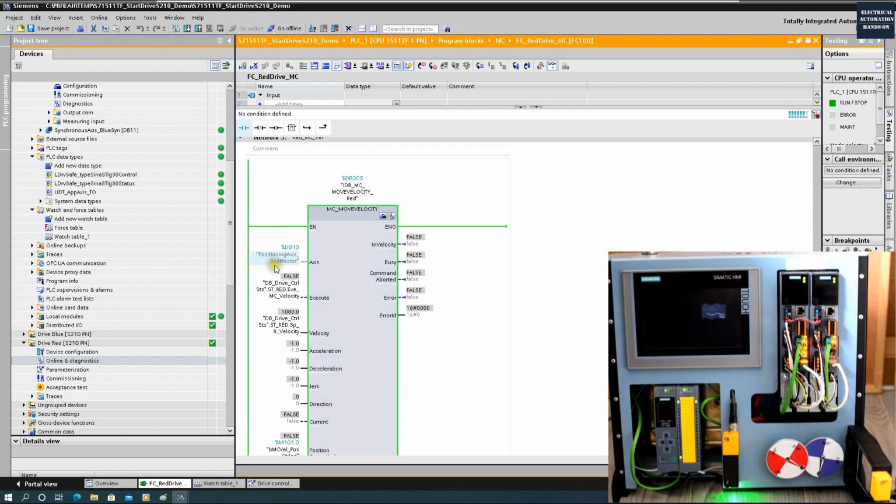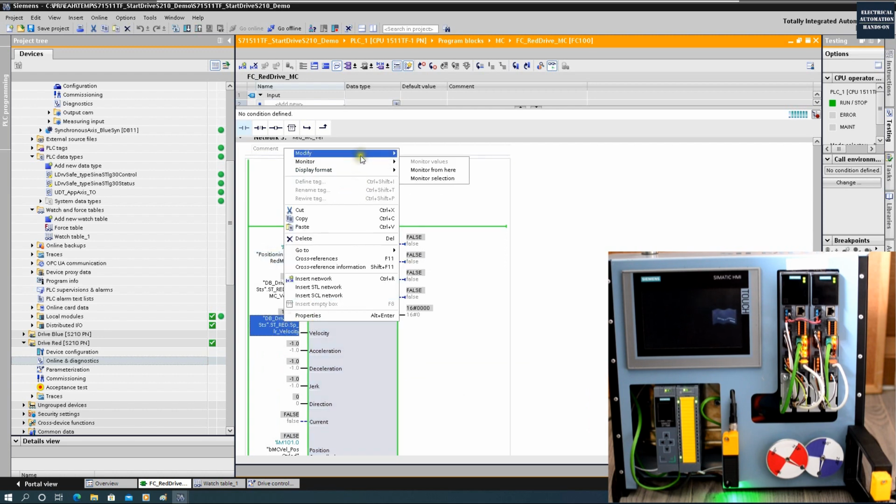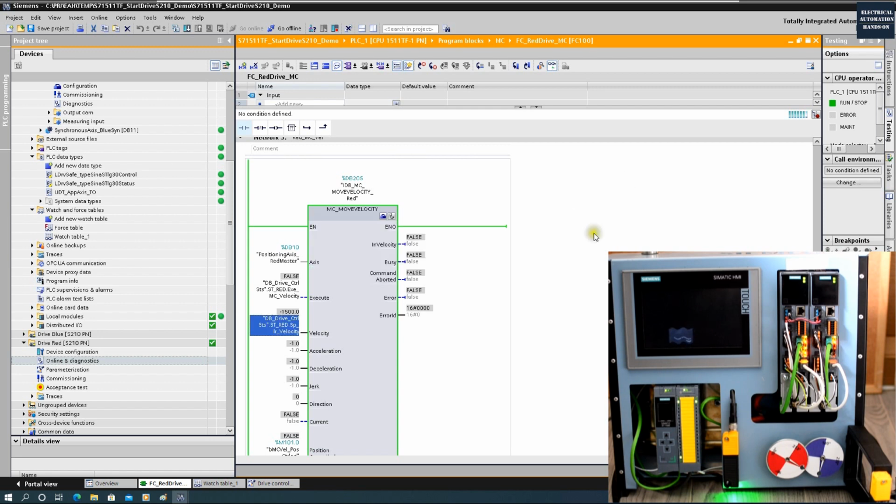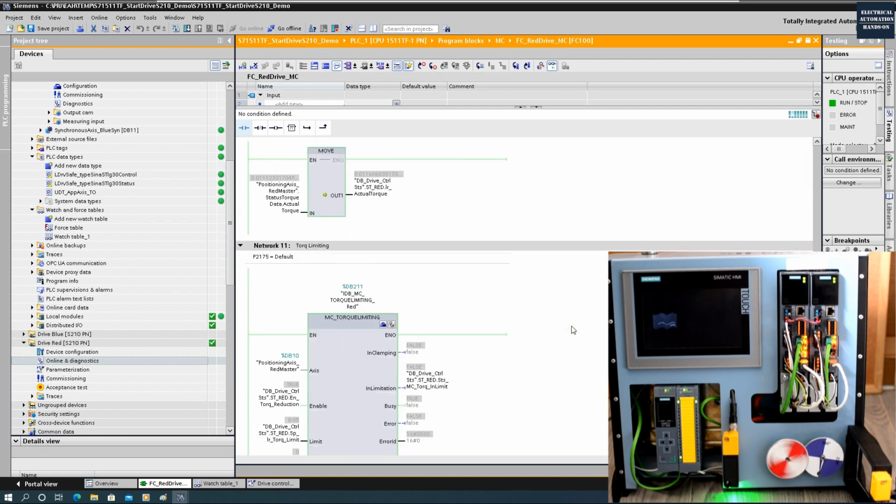And from this move velocity, I can set negative. Let's run faster. Negative 10. Let's run faster. Negative 1500. Okay. Fire. While it's running faster, we will see this torque will show a little bit higher. See here? Before it's below the 0.01. Now it's higher than 0.01, absolute value.